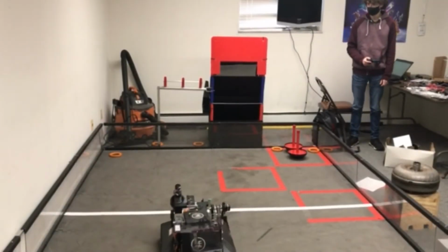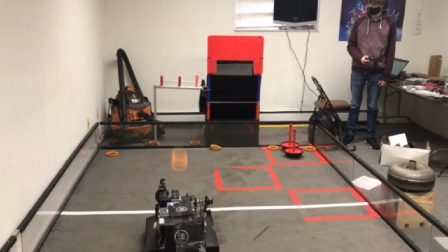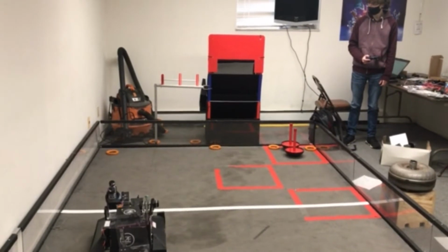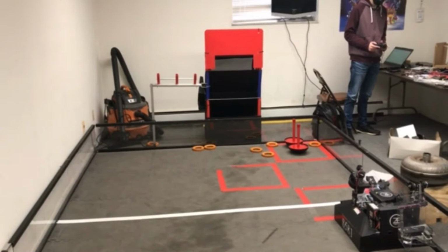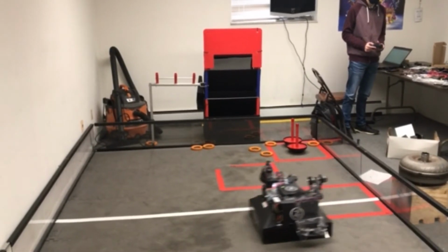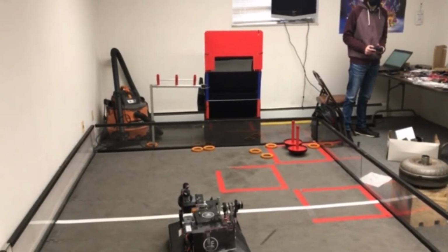We use all the automations above to try and make a smooth experience for our drivers in Teleop. The most useful automation is for power shots. During endgame, drivers line up at the edge of the field, press Y, and let the robot automatically move to the first power shot location. Once a ring is shot, the drivers must repress Y to tell it to move to the next location. Rinse and repeat until all the rings are shot.